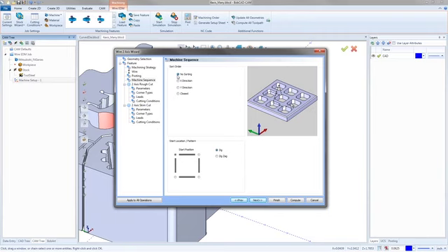So if you drag a box over your part, you're going to get a true no sorting cut. It's going to jump around all over the place. But if you were to go in when you were picking your geometry and you got, let's say, 2D geometry all over the part and you're just cutting pockets or whatever you want to call them, you could just hold shift, click on every cut that you want to make in the order you want it to run. Then come in and say no sorting. It's going to run in the exact order you selected the geometry in. So that's a good way of getting your order set up specifically.